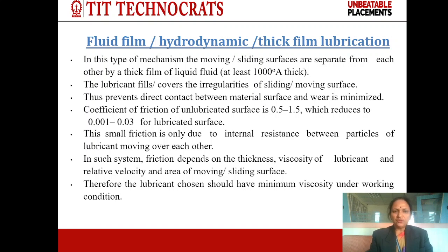minimized. Coefficient of friction of unlubricated surfaces is 0.5 to 1.5, which reduces to 0.001 to 0.03 for lubricated surfaces. This small friction is only due to internal resistance between particles of lubricant moving over each other. In such a system, friction depends on the thickness, viscosity of lubricant and relative velocities and area of moving sliding surfaces.